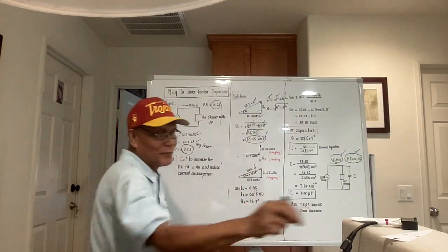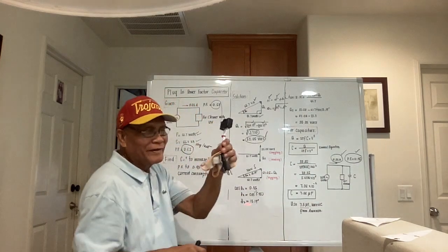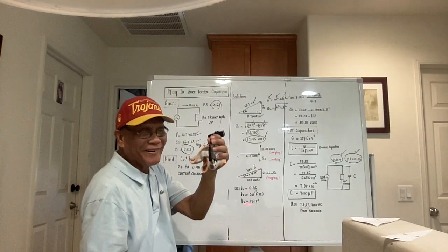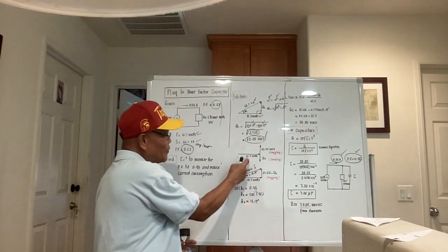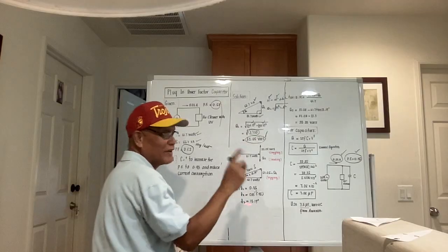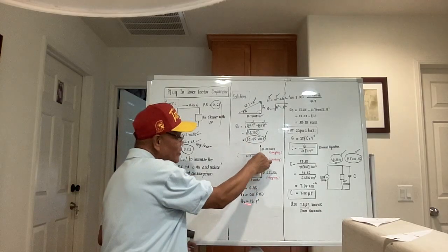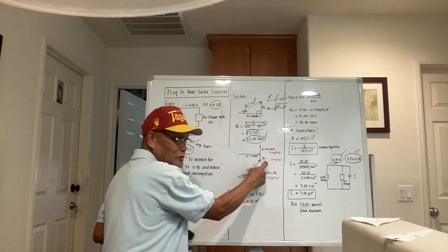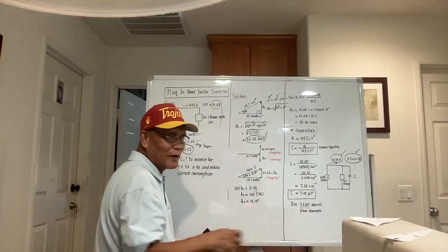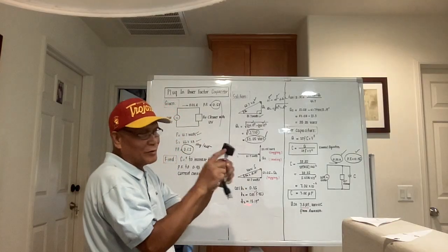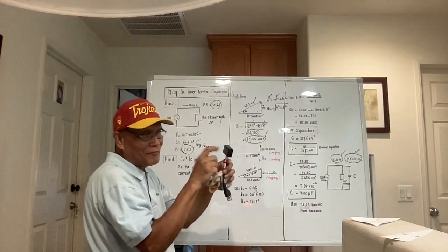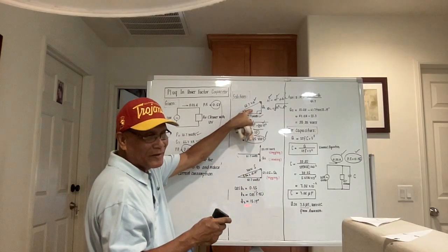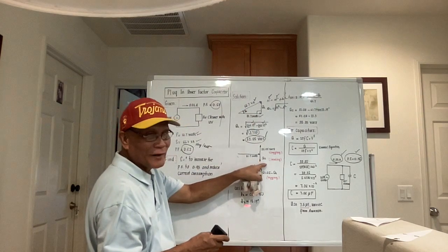And if we plug in the capacitor, it's now a part of the circuit, so there's also a power triangle for this one. Okay? There is no true power, but it has a reactive power. Its reactive power is downward. So this is designated capital letter Q with its subscript C, meaning the reactive power of this capacitor. We need the reactive power of this capacitor to lessen this hypotenuse here. For the meantime, we do not know the value.